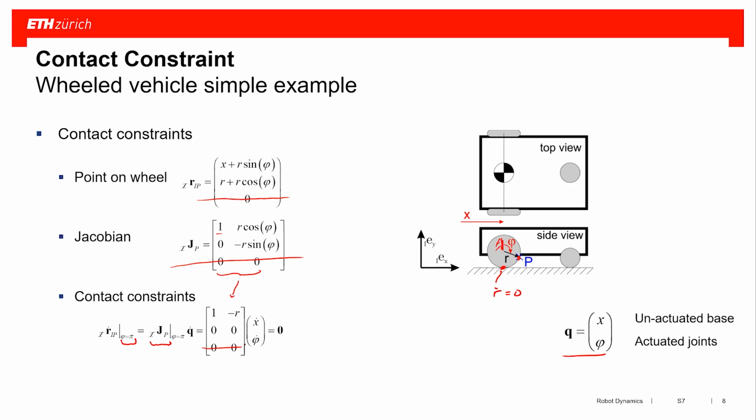Now, why do we use this Jacobian instead of the new Jacobian introduced with the floating base? So this is a floating base Jacobian. We have the floating base, which is described by x. That's why we have the complete Jacobian here. So we have also the x and q in our Jacobian in there.